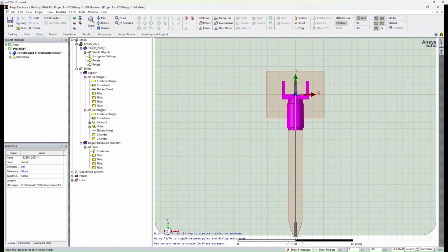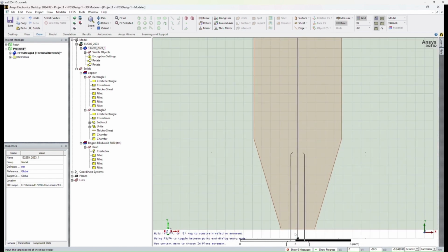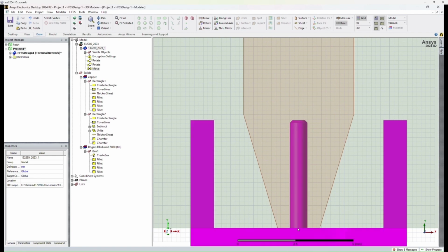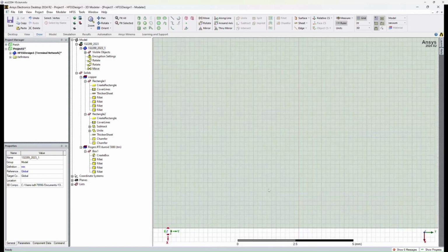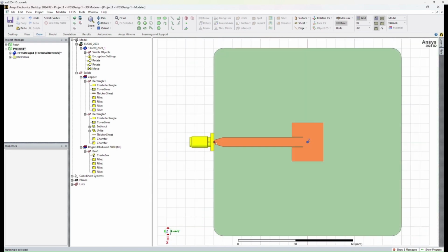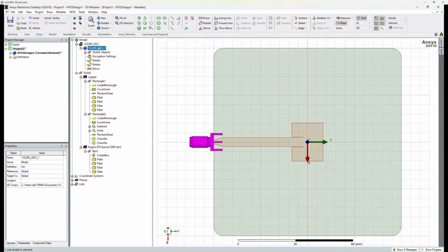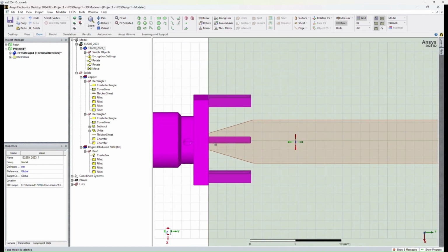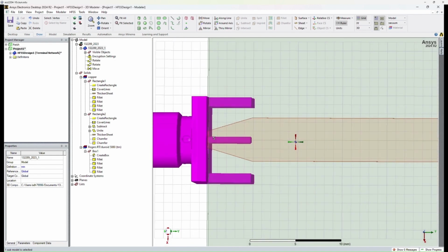And so I'm going to zoom in so that I really select the center edge of this feed network. And then now it's been moved, and whoops, we can see that although it's not positionally right in height, the center pin is aligned to the center of the feed network, and this edge of the connector is mated to the edge of the substrate.